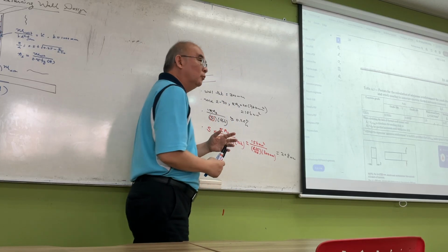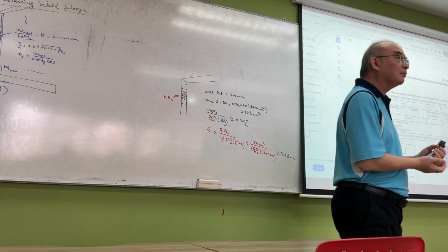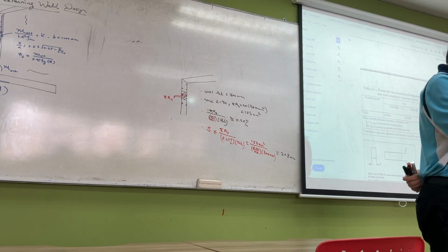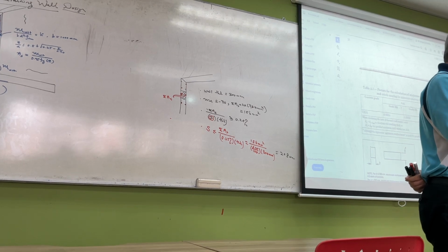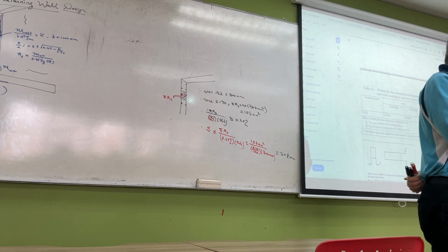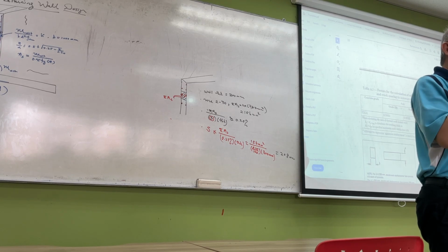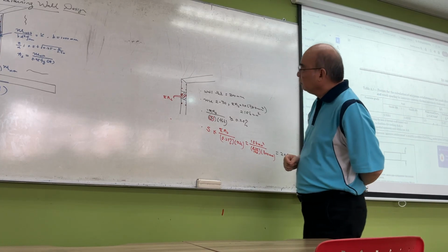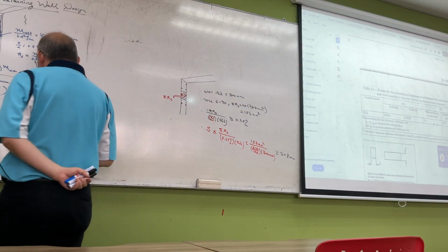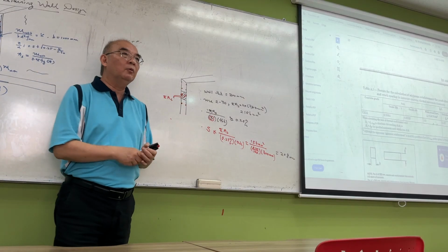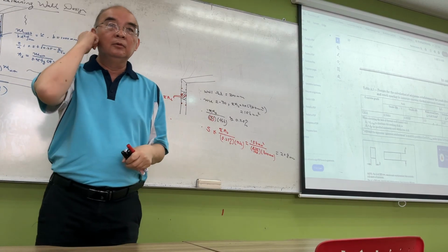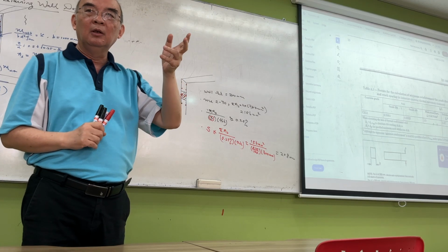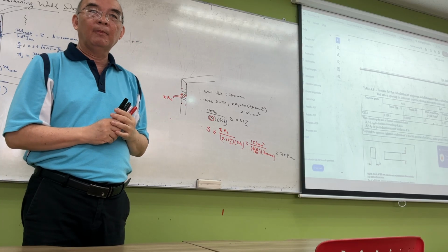You see what I'm saying? Okay. So normally I would choose a bar size first, because normally it is either T10 or T12. Sometimes you go to T16, it's really very thick. Okay, all right. So normally our retaining wall is quite thick, so we will put two layers. If let's say your wall is 125, or 100, normally you just put one layer only. Okay.